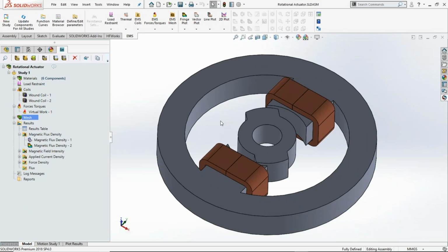Now once the simulation is complete, like I have run this simulation prior to this webinar, we can jump right into the results. But before I go there, I just want to let you know a few things about our EMS solvers. The EMS solvers make use of multi-cores in your machine. So if you have multiple cores, your solver is going to run much more quickly. It also makes use of the RAM. So the higher the RAM, the faster your solution is going to be. EMS can easily deal with several million elements on a very standard computer of 12 GB RAM, i7 Intel based computers, both laptops as well as workstations. And one can do these types of problems in a matter of minutes. For example, to solve this particular problem, it took probably 3 to 5 minutes.